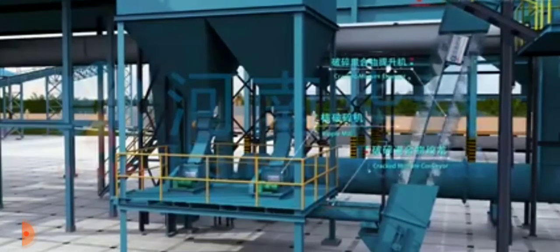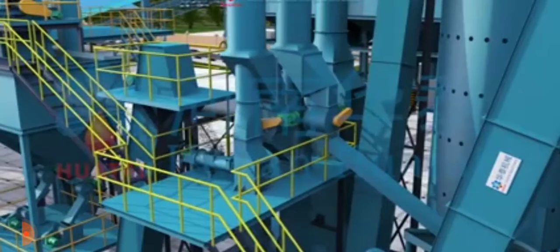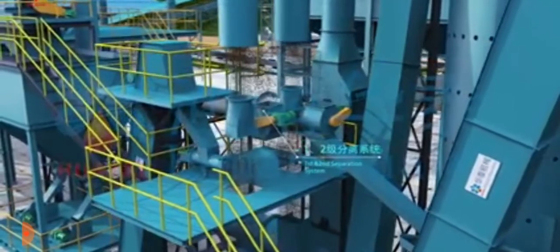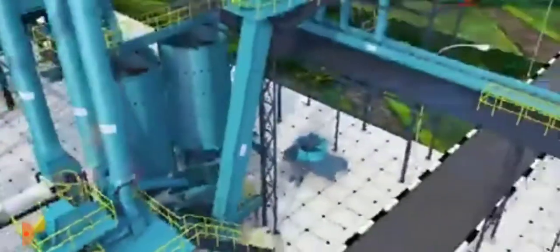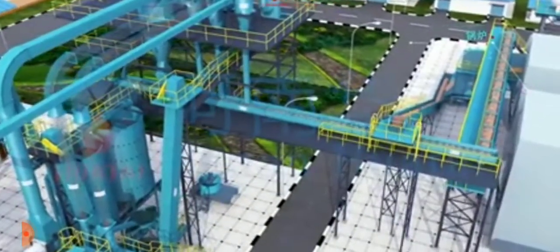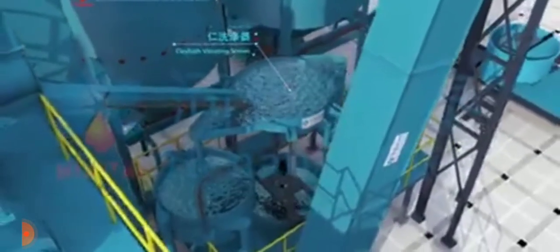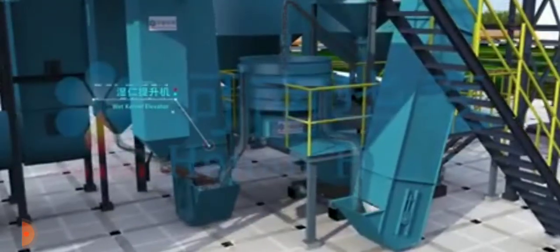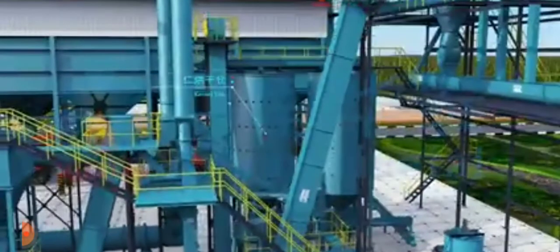Adopt the cracked mixture conveyor and cracked mixture elevator to convey to the first and second separation system. Relying on wind power to separate the shell out and convey to the boiler as fuel. Dumped kernels need to be washed in the clay bath and vibrating screen. Enter the wet kernel elevator together with separated kernel from the first and second separation system. Convey to the kernel silo.